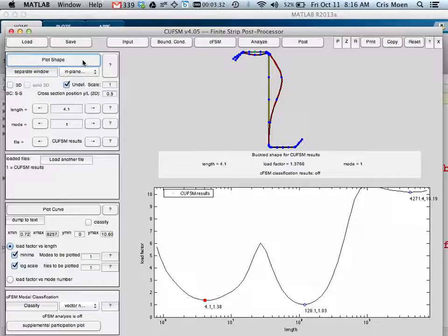This is local buckling. So this is what we would call MCRL. We would grab this off. So those of you who have laptops, can you write that down? That MCRL is 1.38 times MY, and it's occurring at a half wavelength of 4 inches. And that's very typical. For a flexural member, when you have a depth of 8 inches, the half wavelength will be half of the web depth. That makes sense. You'll have the bubbles occurring at 4. Then let's go over here.